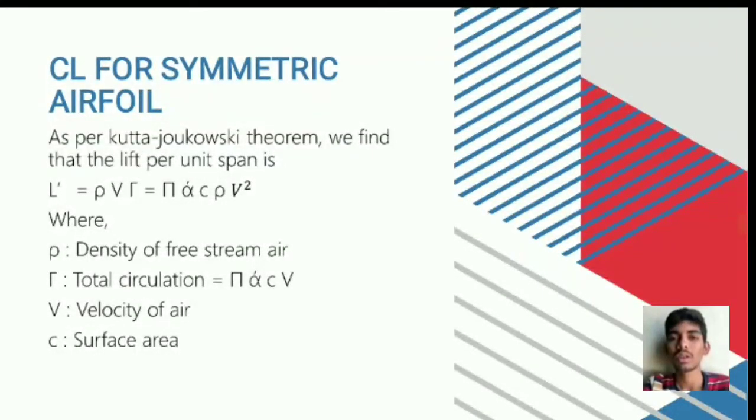Next, coefficient of lift for symmetrical airfoil. As per Kutta-Joukowski theorem, we find that the lift per unit span is equal to rho V Gamma, where rho is the density of free stream air, and Gamma is the total circulation, which is equal to pi alpha c V, and V is the velocity of air, and c is the chord.